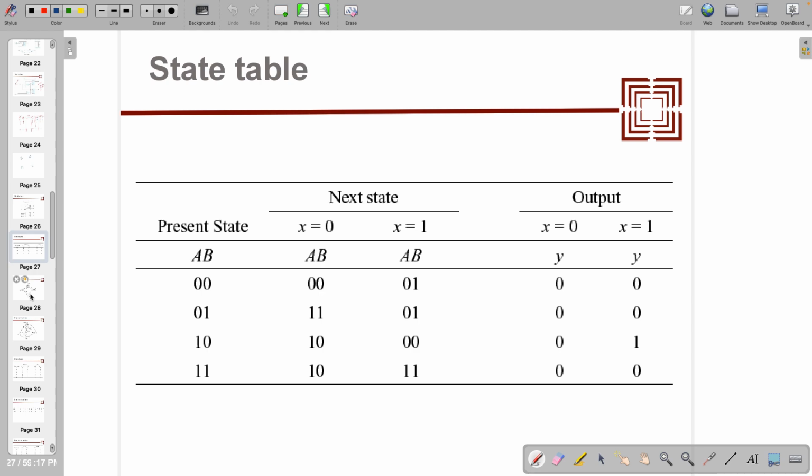Okay. So there is another example where present state and next states are written. When there are present states of A and B, how many flip flops are required in this case? Only 2, right? Because 4 combinations will give you 2 flip flops. Note that there is no unique answer in terms of all these questions, because you can solve all these questions with different combination of present state and next state. Right now, for this question you will get the unique answer.